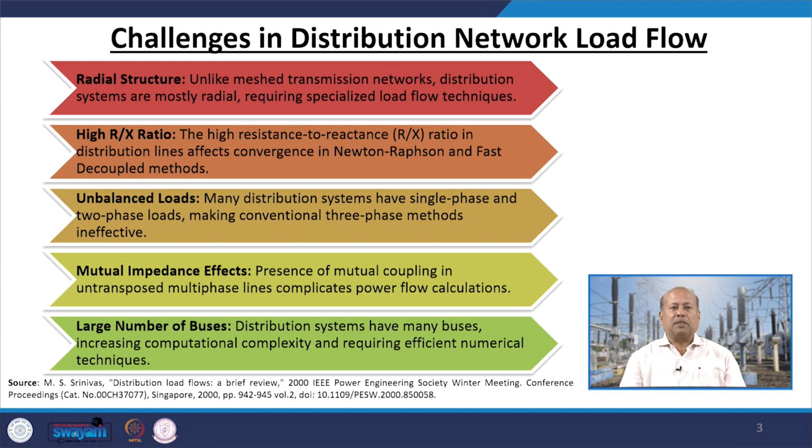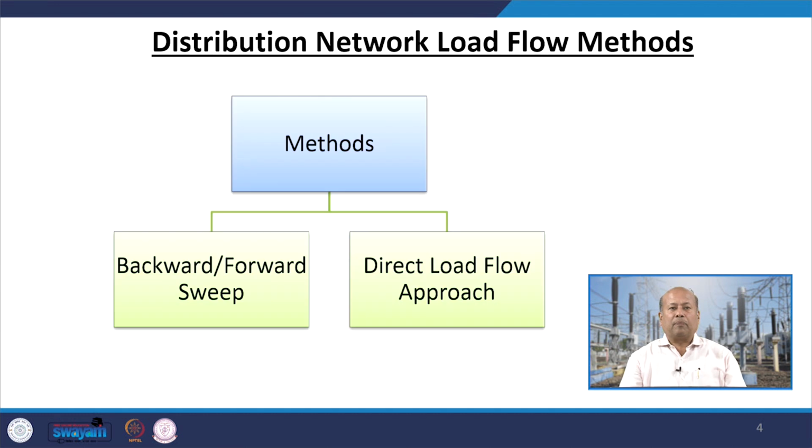Many distribution systems have single phase and two phase loads, making the conventional three phase method ineffective because the system is purely unbalanced. The presence of mutual coupling in untransposed multi-phase lines complicates the power flow calculations. Distribution systems have many buses, increasing computational complexity and requiring efficient numerical techniques to solve load flow analysis.